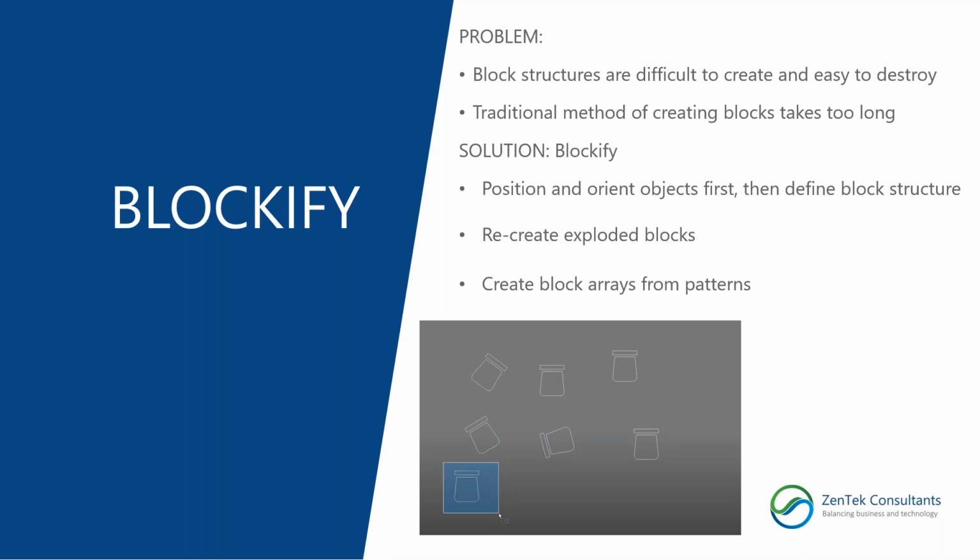One of the things that you can do with Blockify is draw your repeated objects before creating the block structure. So you can make copies of your object, place them in various different orientations, and then use Blockify to turn every single instance of those objects into blocks. So that's one of the uses of Blockify.